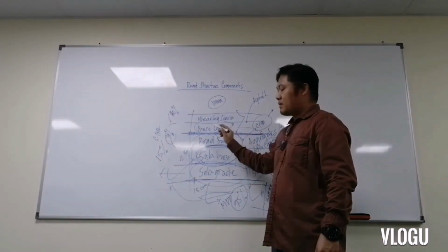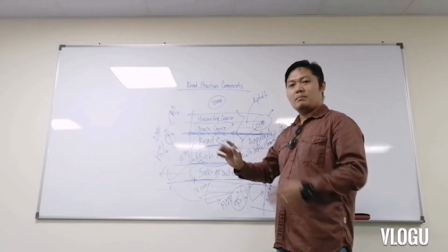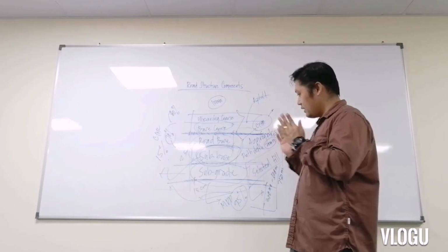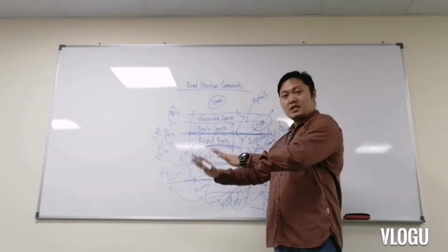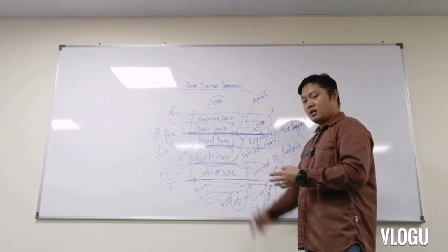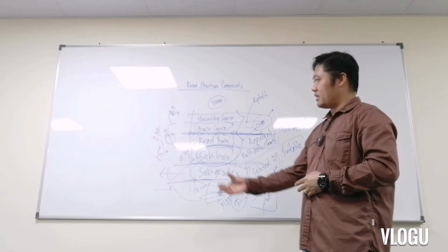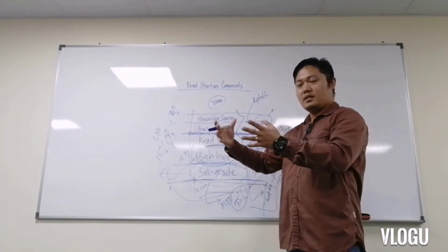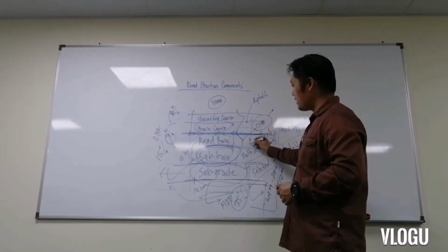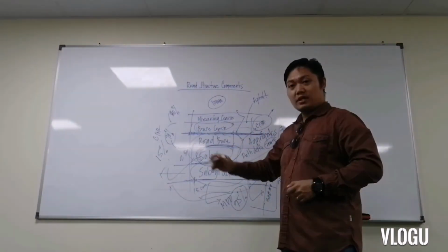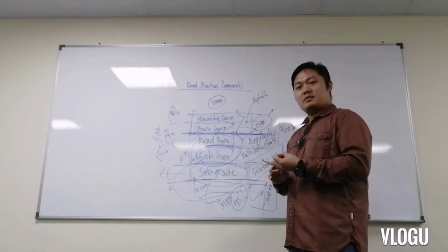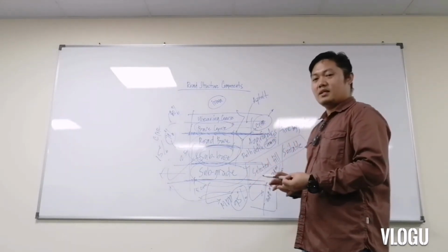The asphalt laying will be done using a paver machine to ensure even spreading and that no segregation happens when we lay the asphalt. Each delivery of asphalt is normally measured in tons. They identify the particular locations, and based on each location, they spread the asphalt either by feeder machine or by paver machine.